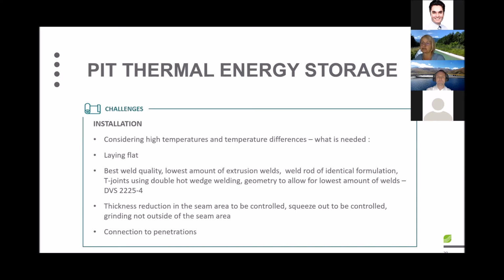So if we are installing such an application, we are following strictly DVS 2225-4, which is the guideline for landfill lining in Germany, but it's also applicable for PTES. It is to be addressed that the thickness reduction in the seam area needs to be controlled. The amount of squeeze out needs to be controlled in order to not have a lot of squeeze out, which is then at the end acting as a notch in a geomembrane, for example, which is a critical area considering high heat or temperature changes.